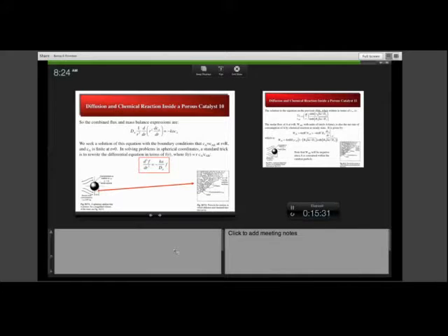So with the differential equation, we seek a solution where the concentration of A is equal to C_AR right at the boundary, and C_AR will be determined by the bulk phase concentration of A surrounding that particle. It will also be dependent on how important the boundary layer is in taking that bulk phase composition down to the composition right at the surface.